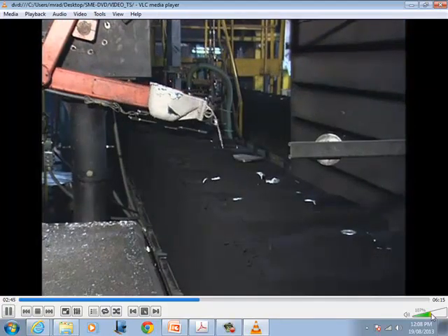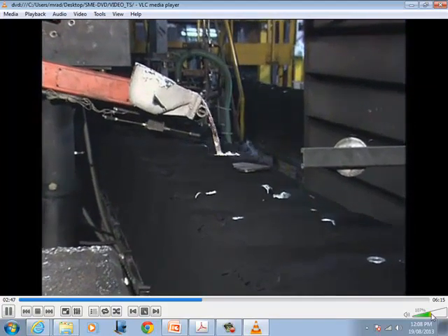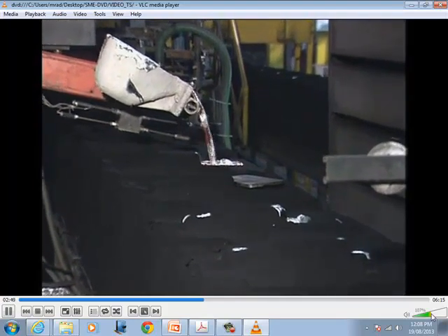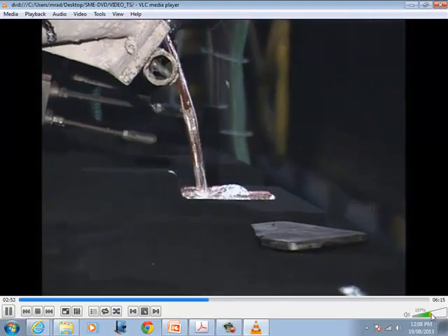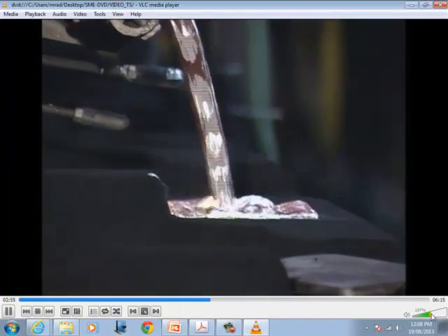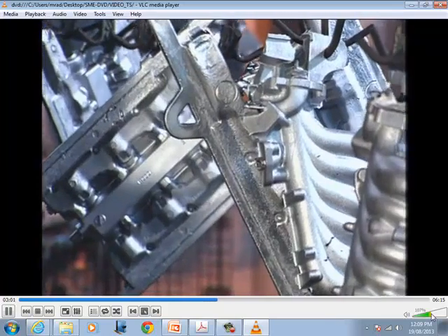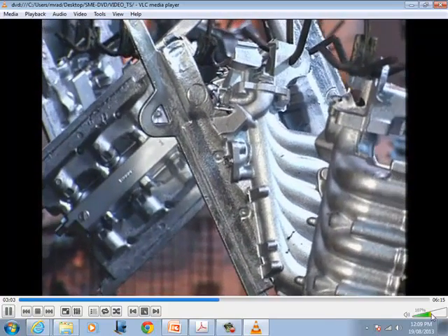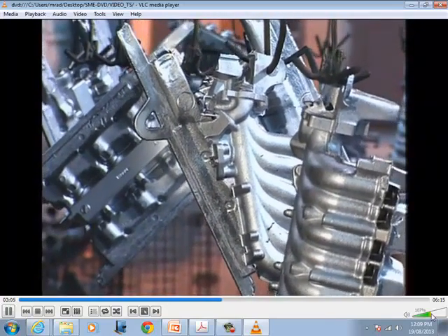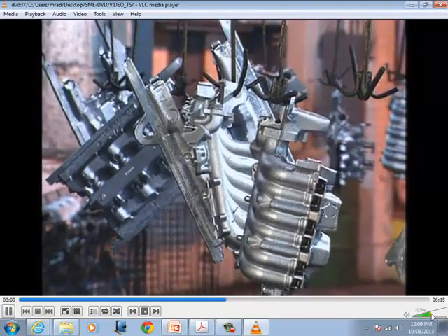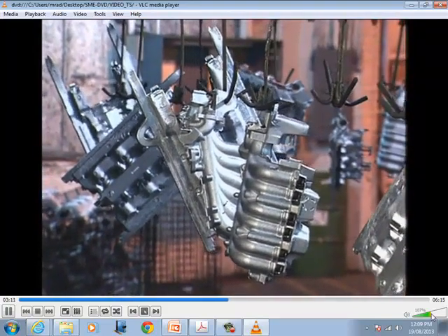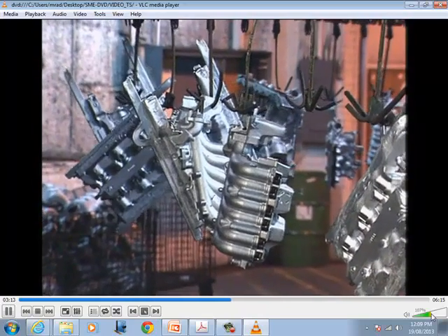Although casting in green sand molds is a versatile process, thin sections are difficult to cast because they may be eroded by the molten metal, or the metal may cool and become solid before filling the sections. Also, part tolerances and machining allowances must be rather liberal. Very smooth finishes are not attainable, and certain metals can develop defects if cast in molds that contain moisture.